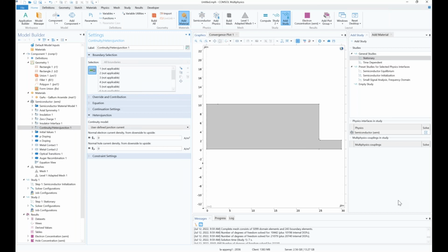You want to model metal and the electric in the multiphysics coupling, that's what you mean? That's a good question. For instance, in this example, this LED will only simulate a semiconductor. We do not really simulate metal. We just use a boundary condition to represent metal. Sometimes users do want to include metal in the system. Definitely you can.